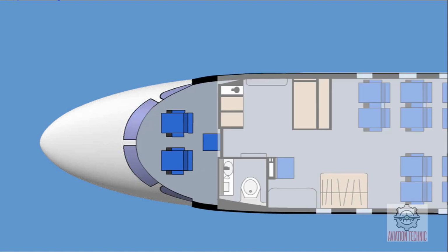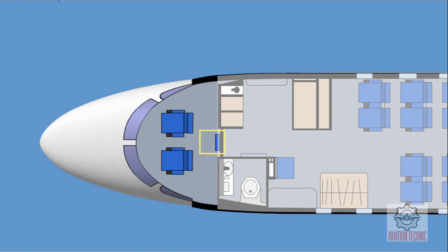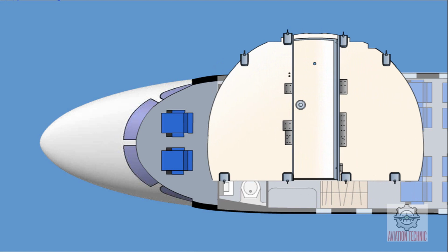The general cockpit interior provides an ergonomic working space for 2 pilots, 1 observer, and also storage of working and emergency equipment. The cockpit is configured as follows: 2 pilot seats, a foldable flight observer seat positioned just in front of the cockpit door. When not in use, this seat stows behind the pilot seat. A cockpit bulkhead with a lockable door.